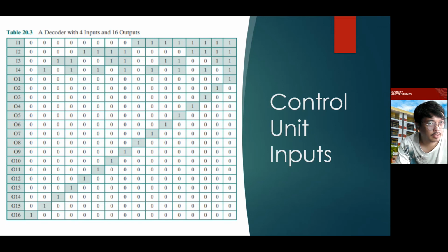And the clock portion of the control unit issues a repetitive, continuous sequence of pulses, and this is useful for measuring the duration of the micro operations. Essentially, the period of the clock pulse must be long enough to allow the propagation of the signal along data paths through the processor circuitry.